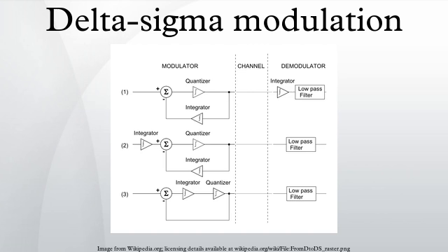C, the current into the capacitor, IC, is the linear sum of the impulse voltage upon R and van upon R. To show this sum as a voltage, the product R, IC, is plotted. The input's impedance of the amplifier is regarded as so high that the current drawn by the inputs is neglected. D, the negated integral of IC. This negation is standard for the op-amp implementation of an integrator and comes about because the current into the capacitor at the amplifier input is the current out of the capacitor at the amplifier output, and the voltage is the integral of the current divided by the capacitance of C.